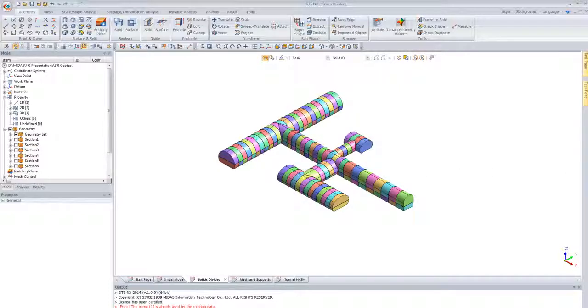Right, I just want to bring it up. So can non-horizontal ground layers be created? Yes, we can. You can include borehole locations from a DXF file as well, making it easy to import and bring across. You can also define the ground layers by inputting the upper and lower bounds of each soil type.